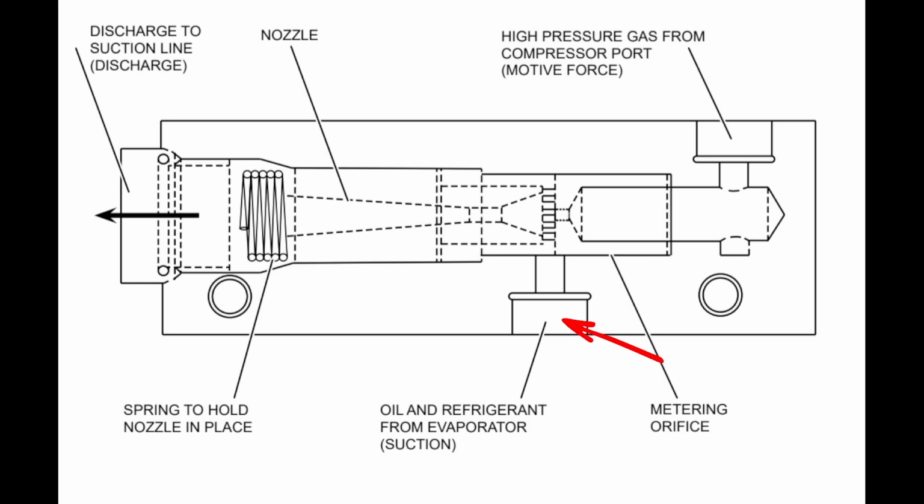So we want refrigerant that has a high concentration of oil in it, or potentially a high concentration of oil, so that we can then inject that into this pump on the suction port of it, so that it will push that oil latent refrigerant into a vapor state back to typically our suction line or our oil reservoir, depending on the compressor and the design of the system.